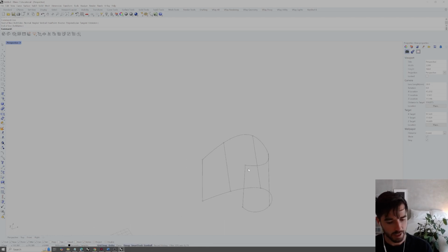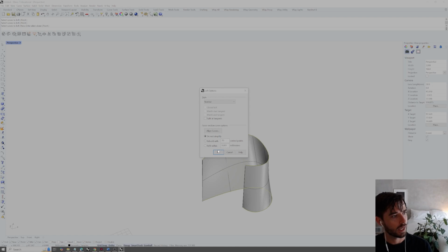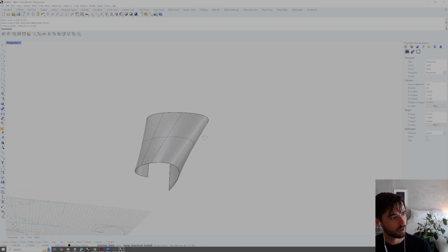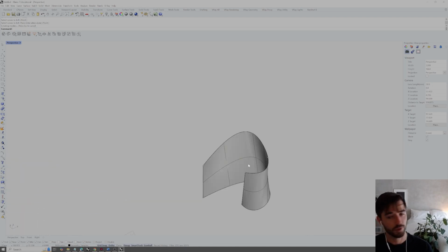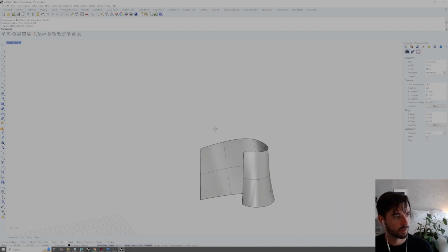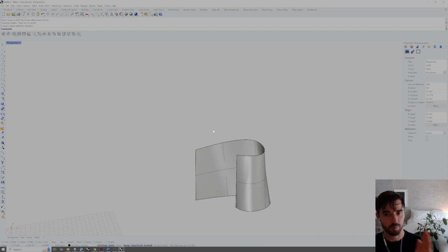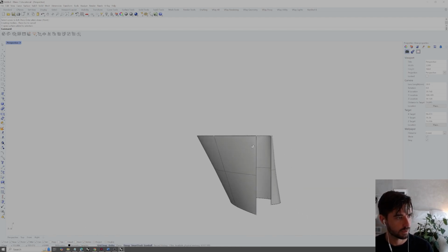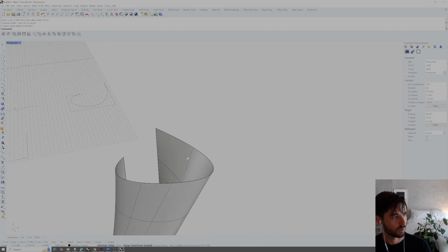So in order to get that, we can just type loft, and it's going to ask us for the curves to loft. We can select one curve and then the next one, hit enter, and then hit OK. And it's now going to define that lofted surface with infinitesimal resolution, meaning it's a kind of solid, opaque surface inside of Rhino, which is really just a very tight bundling of those curve definitions drawn out as connections between those 2 curves.